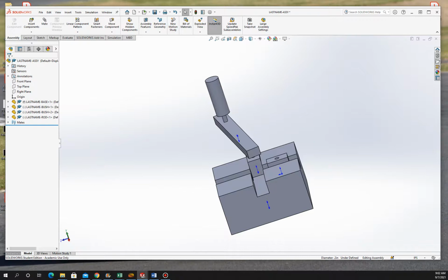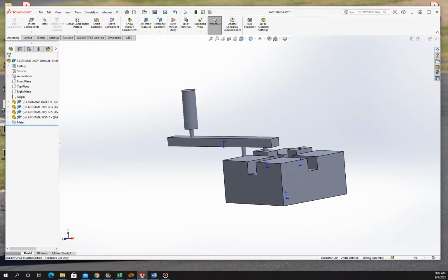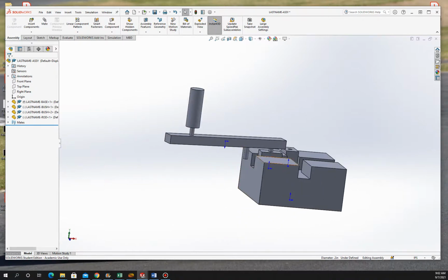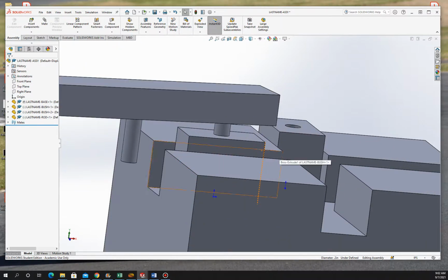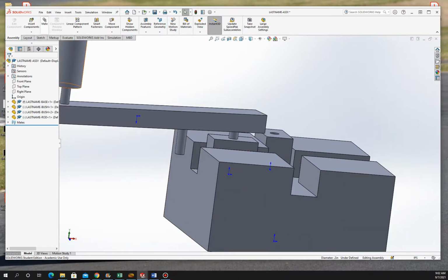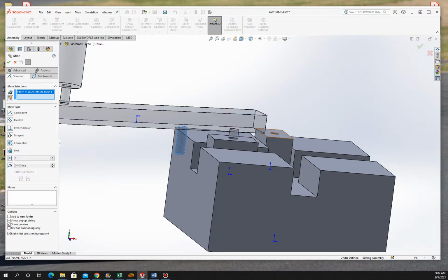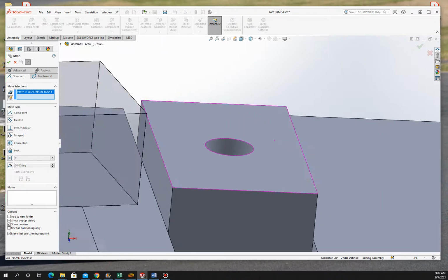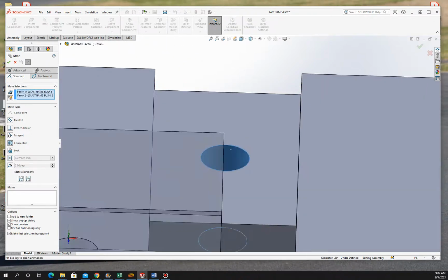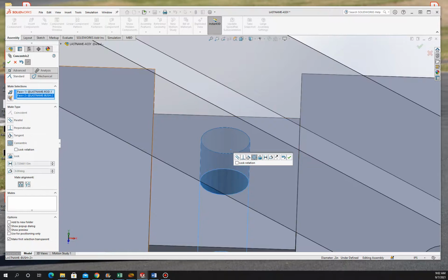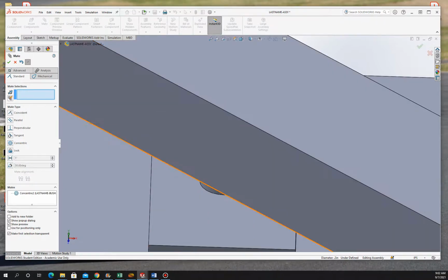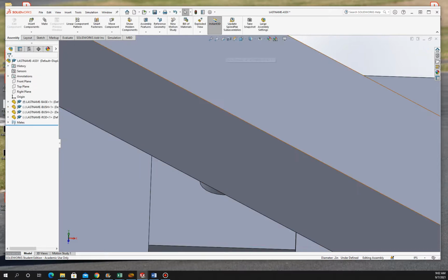Next thing, now we've already determined earlier, because we know the blocks are the same, that we don't have to set the depth right now. So mate, we're going to grab the outside diameter of the other extrusion, and then we're going to zoom in, possibly rotate a little. We're going to grab this, right? And you can't really see what's going on, but we're going to hit happy check mark. Hopefully everything's worked. Happy check mark it again.